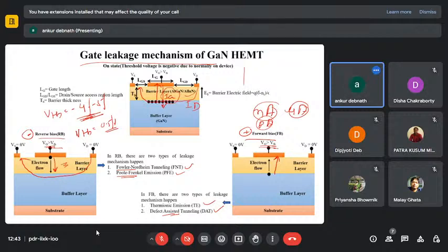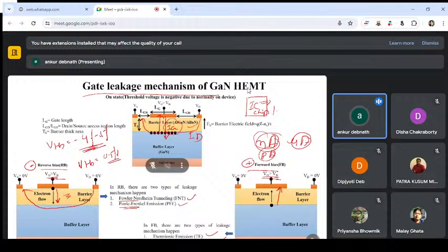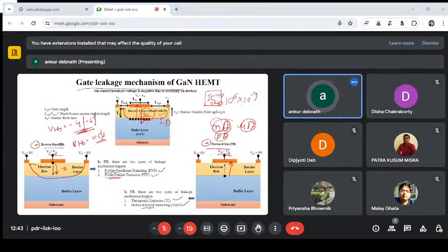Now nanoampere is very little current, right? But in an IC chip, there are millions or billions or even trillions of transistors. If you add up all this leakage current in the nanoampere range, with millions of transistors, that is 10 to the power 6 times 10 to the power -9, so the current is high. That's a milliampere of current, a significant amount that we don't want, but it is inside the device.